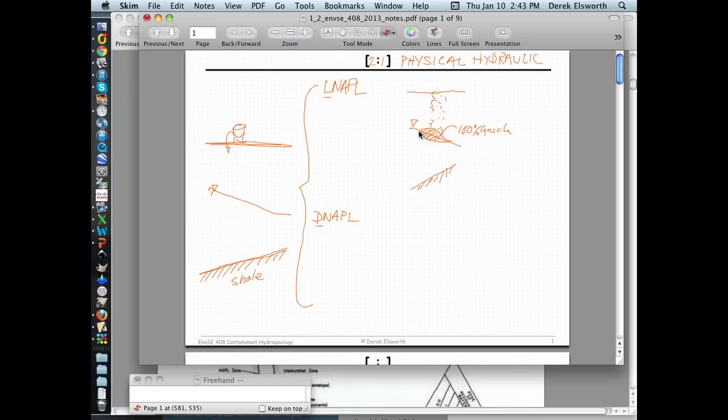But it could dissolve in the water, and if the water table is going in this direction, the hydraulic gradient is a positive hydraulic gradient, and we know that velocity by Darcy's law is equal to minus hydraulic conductivity times the hydraulic gradient, and that velocity is a vector quantity. In terms of the x and y coordinate system, a positive gradient would be this. This is a negative gradient. So a negative gradient times a negative gives a positive velocity.